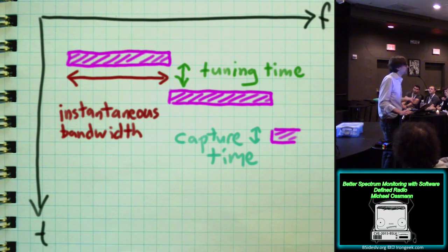With some optimization, my best case, I think, is about 150 microseconds. So in certain frequency bands, I really can tune super fast and reduce a lot of that transient time, that time during which I can miss transients.